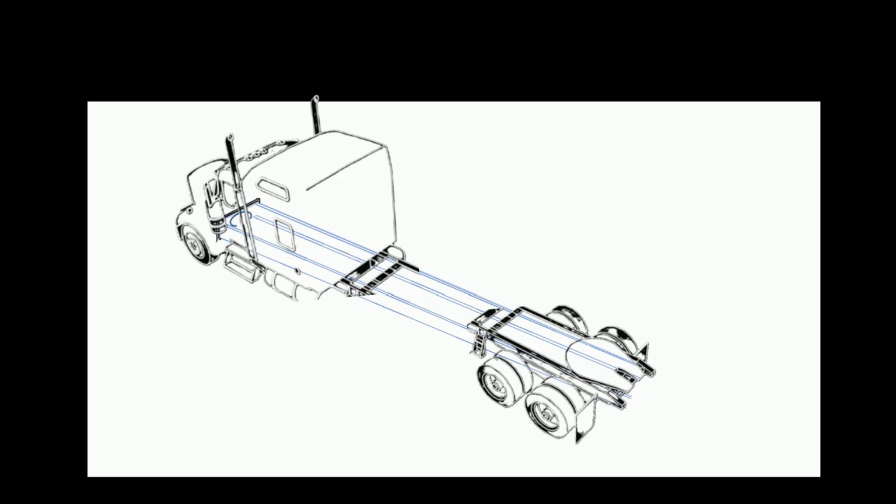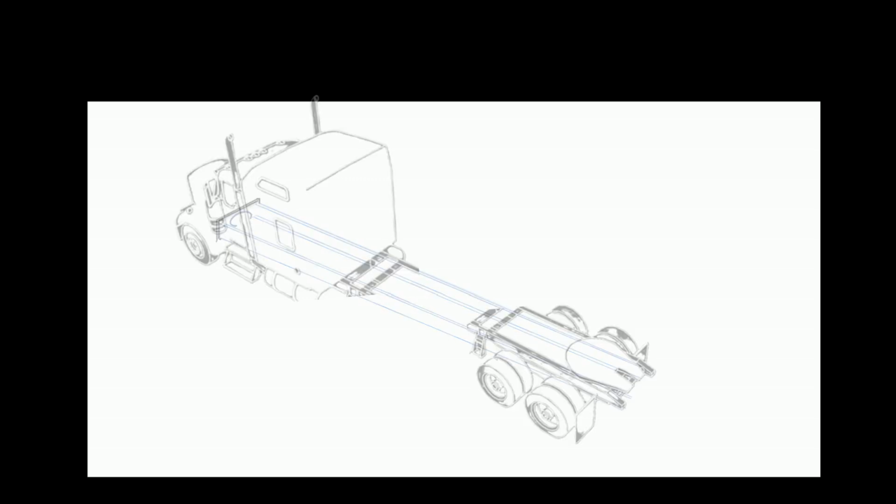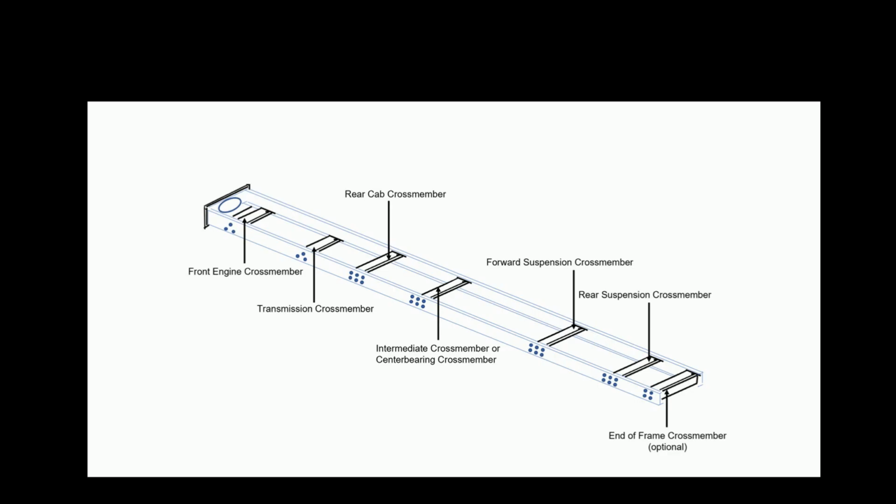The placement and style of cross members are determined by application requirements and chassis design. Cross-member spacing is regulated by maximum distance requirements, stated in inches. An intermediate crossmember may be unnecessary if a center-bearing crossmember is required. This fluid interaction makes predefining the center frame challenging for design teams.